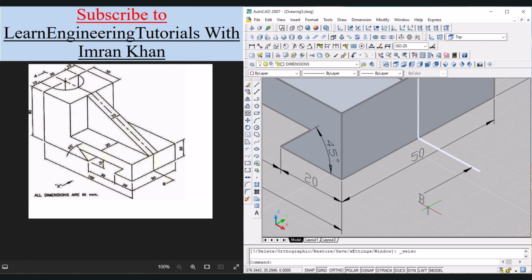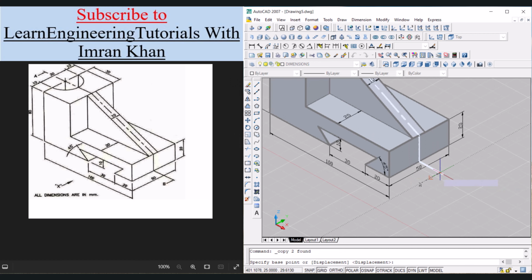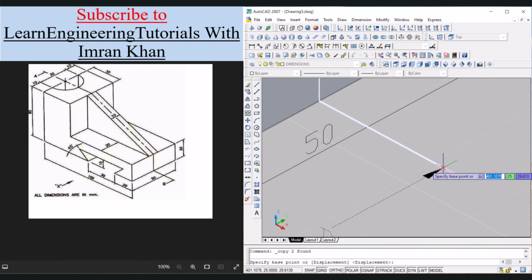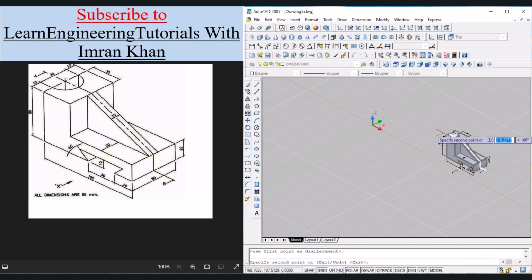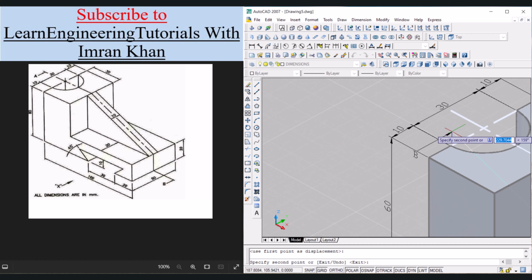Now click on these two, click on copy, click on the base point to be this intersection, click over here, and also we have to drag this line and click. Press escape.